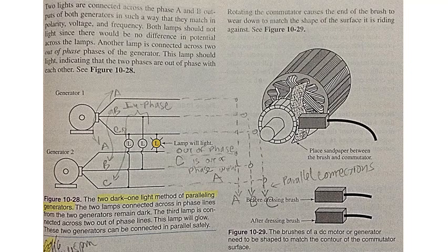A bluish burn pattern will be evident. Excessive brush wear can be determined by physical inspection. The measurement for minimum brush length for a generator can be found in the owner's manual. The brushes should be replaced if excessive wear is found. When replaced, brushes should be dressed.